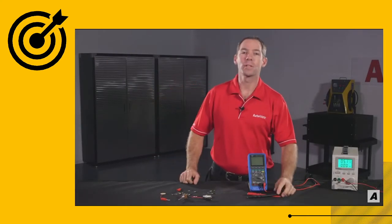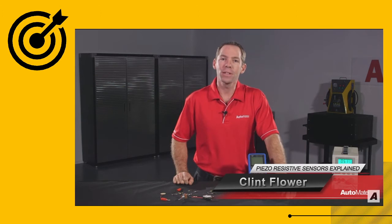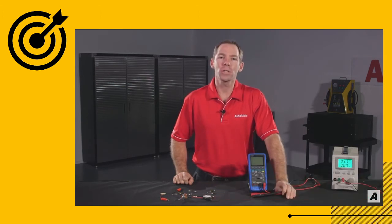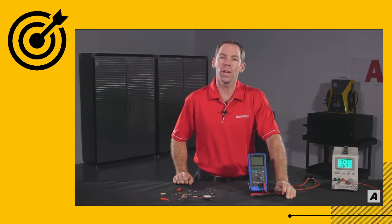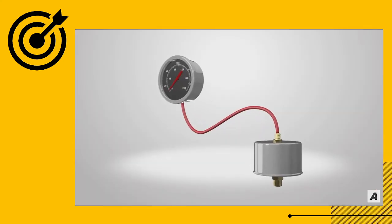Hi, I'm Clint. Welcome to Automate. In this video, I'm going to simplify and explain piezoresistive pressure sensors. Since the introduction of electronic control over fuel and ignition systems, pressure measurement has been required. Most early systems used a mechanical pressure sensor consisting of a diaphragm connected to a potentiometer. As the diaphragm moved due to the pressure change, so did the resistance value of the potentiometer.